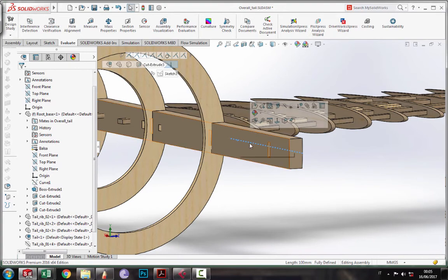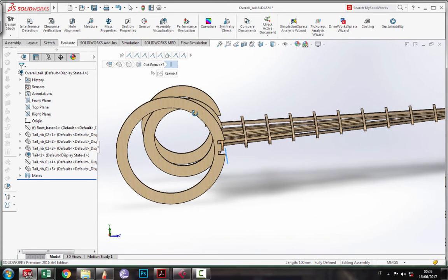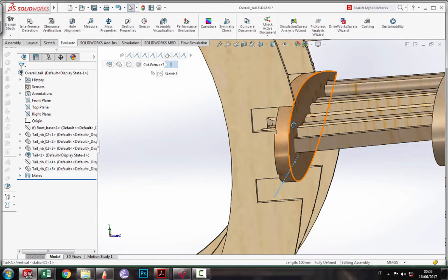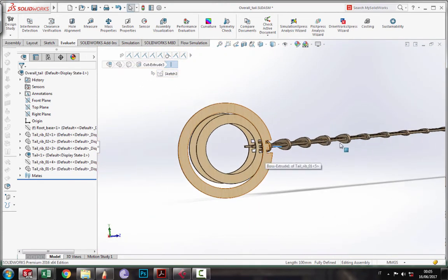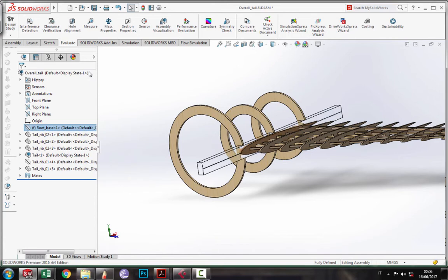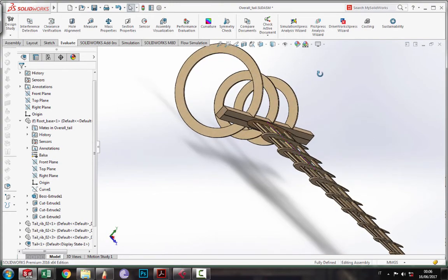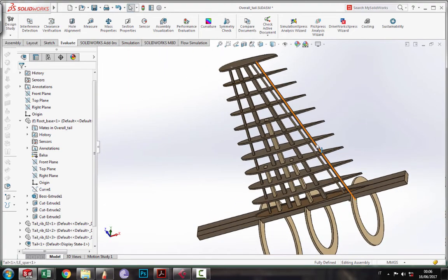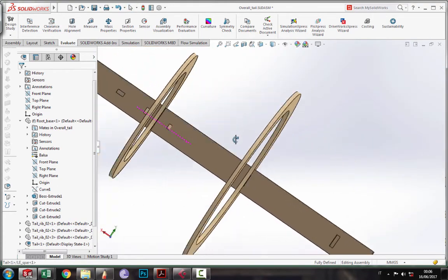And we have all these ribs of the fuselage, which are done in this way in order to lock the structure, you know. So if you glue all this part, all this system will be a unique part, it cannot rotate, it's very stiff. Then, in the end of all, you will cover all with this, but okay, it's fine. So I think this is all you need to know about how to build a vertical wing.